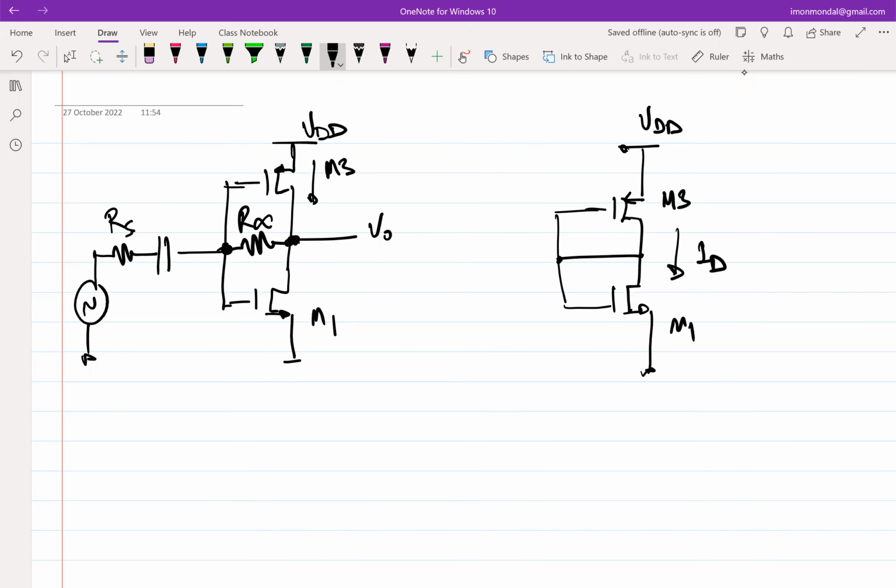Okay, you can keep it open circuit, but if you keep it open circuit, what is the relation between, let's say, VG and VD? At DC, what do you expect this relationship to be? I am transforming this to this, right? So on the left-hand circuit, what do you think is the relation between the gate and the drain at DC? They're equal, right? But if you keep it open circuit, then it's not equal.